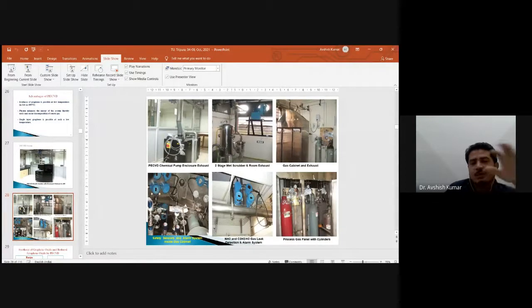And the gases which we use with this system are toxic, particularly ammonia or hydrogen that we use as a carrier gas. So a two-stage wet scrubber is attached with the system, and once the growth process is over, those gases pass through this wet scrubber and then go to the environment. The main purpose is to remove the toxicity of these gases so that they are not harmful.